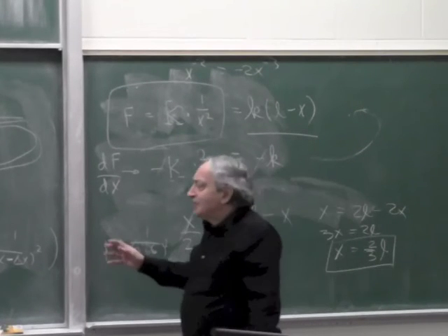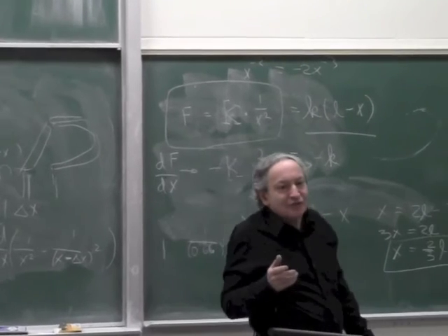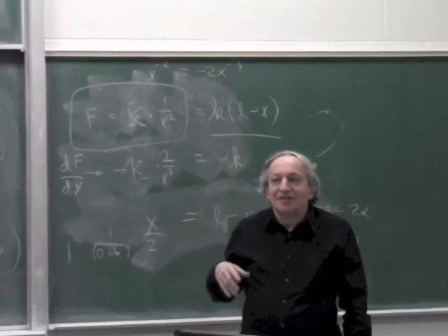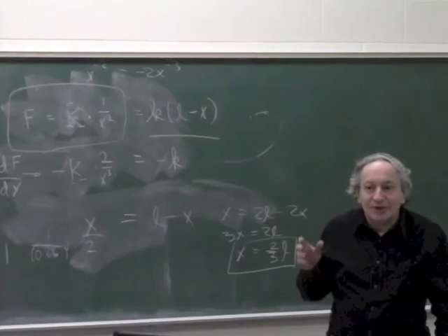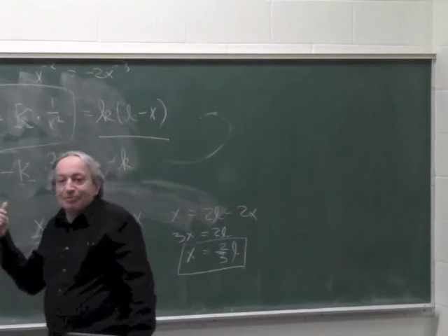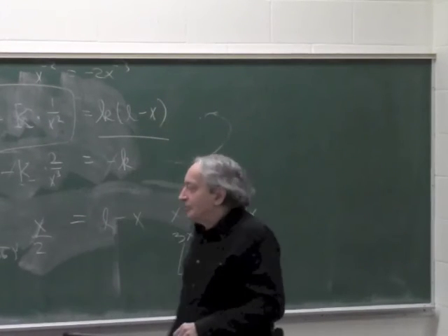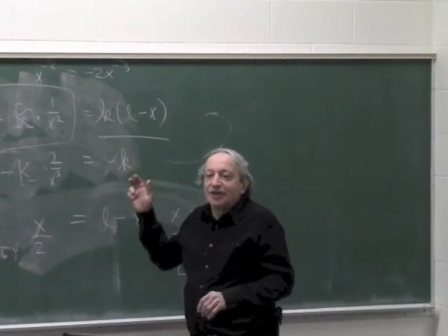So this explains why non-linear actuators are not used much in servo, although they're cheap and simple and don't need sealing and don't demagnetize. They have every possible advantage, but they have one killer disadvantage: their gain changes and they snap. Okay, clear? Good. Okay, now let's see if you followed carefully.